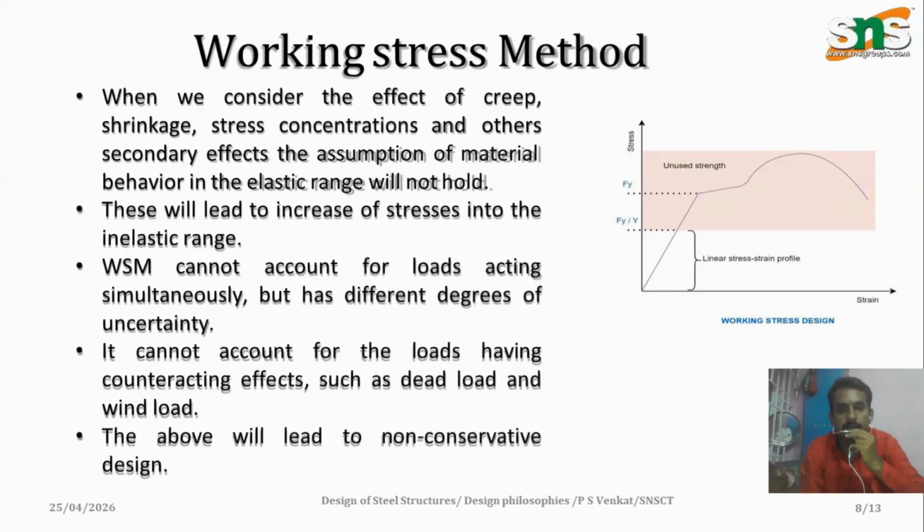The limitations of working stress method are: it assumes purely elastic behavior, which is not always true. It cannot handle multiple loads acting together effectively. It ignores secondary effects like creep, shrinkage, and stress concentration. Because of these reasons, it may lead to unsafe or non-conservative design in some cases.